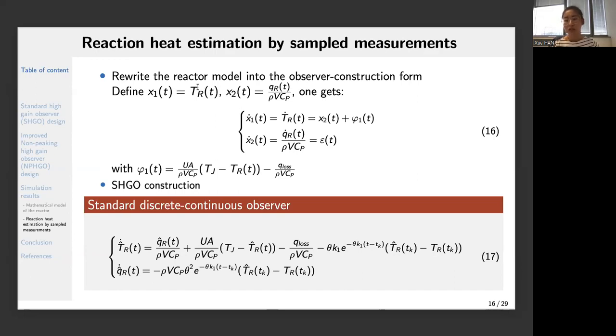It is a very complex function of the reaction speed and the temperature. So we use the easiest way, the observer, to estimate the state we don't know. For me the most important is the temperature, and the other states are not easy to obtain, compared to the temperature.